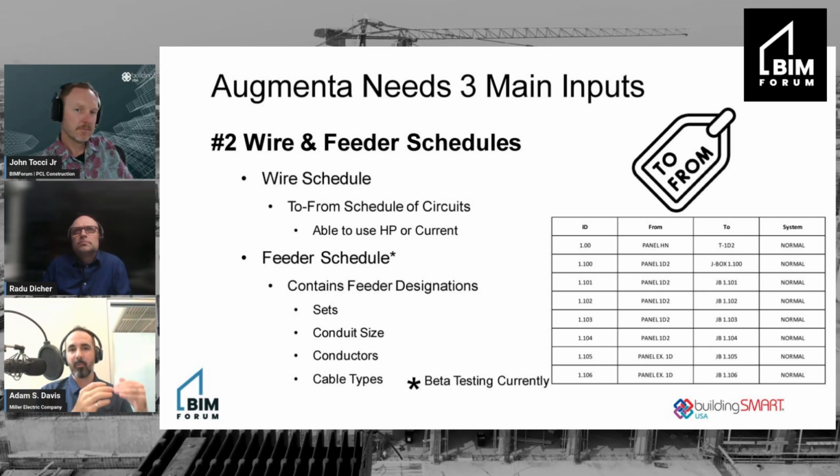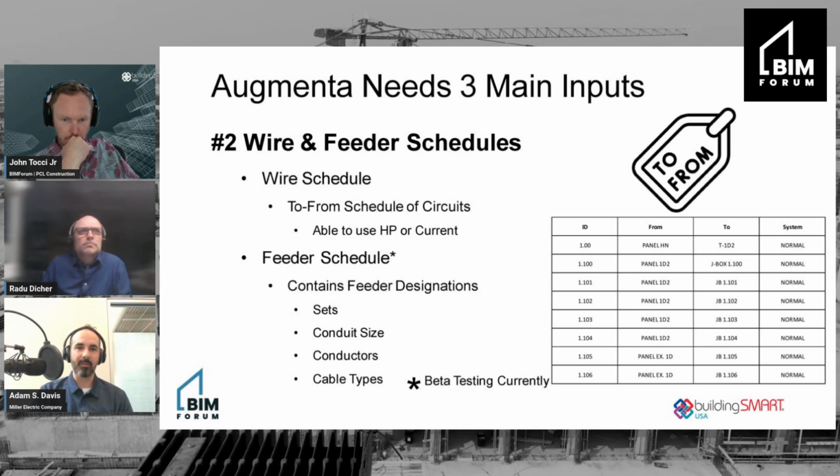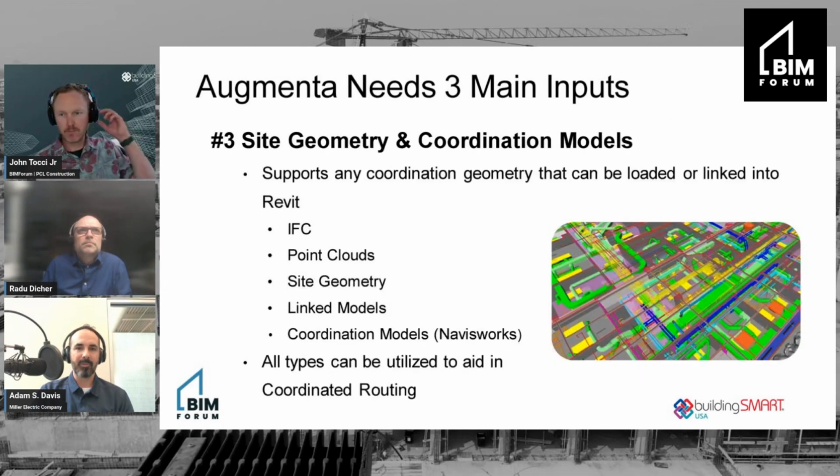It'll have a full-blown feeder schedule with sets, conductors, cable sizes, jackets, things that help with some of that specific conduit fill ratio or tray fill ratio type things that we look at. But today it's leaning on the electrical knowledge of whoever's inputting those things to make sure that we're not over evaluating or over leveraging those systems. So it's like today, tomorrow.